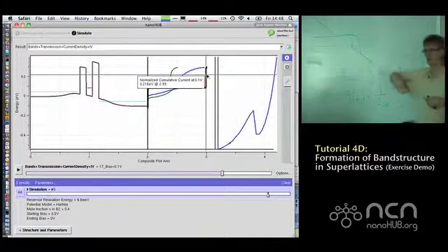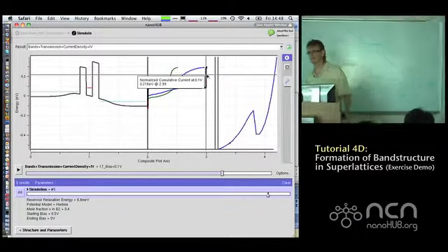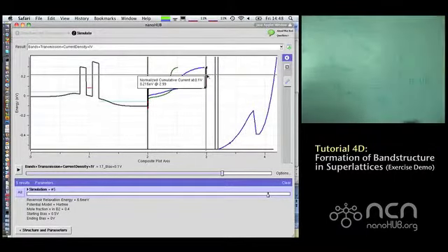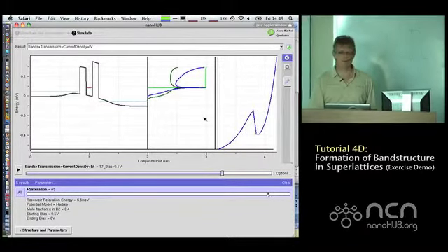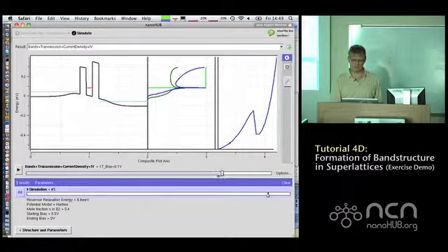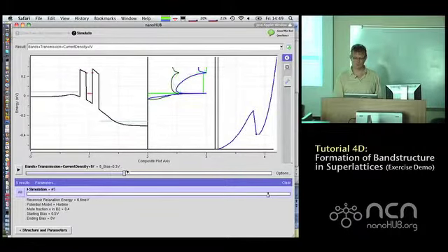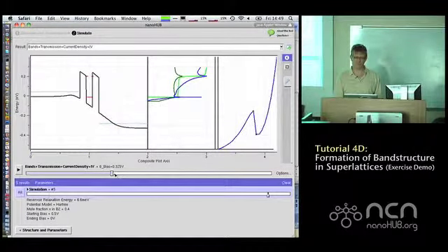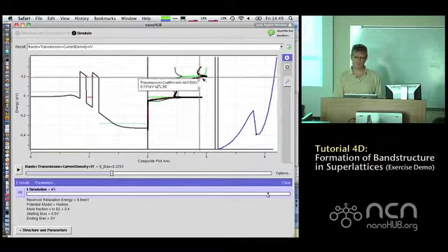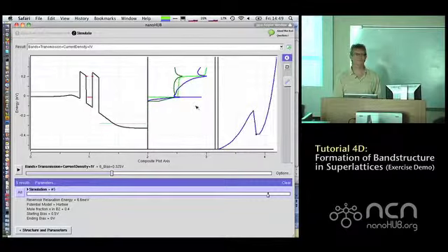And whenever there's a strong contribution, I will see a step. And whenever I don't add much, there's no addition, and it just is a flat curve. Does that make sense? That then allows me to identify really easily where current is flowing. So you can see right here's a strong difference between peak and valley. At the peak, there's a lot of charge flowing through this ground state resonance. And if I am in the valley, the resonance has basically emptied out, and most of it is running through the upper state now. Does that make sense?